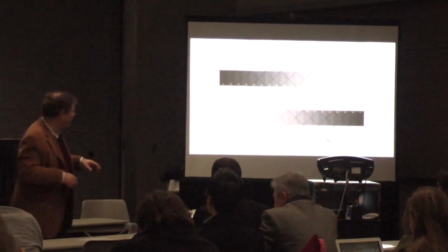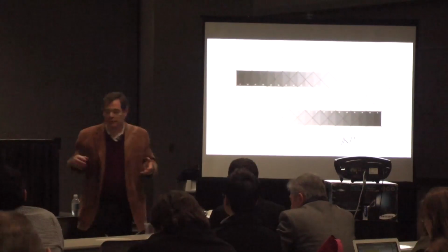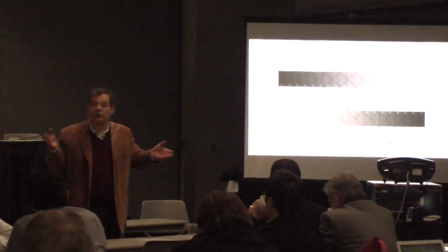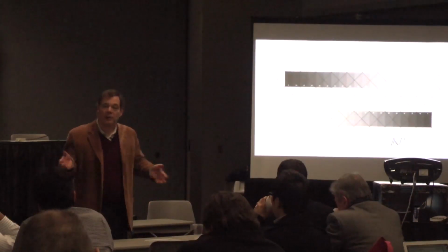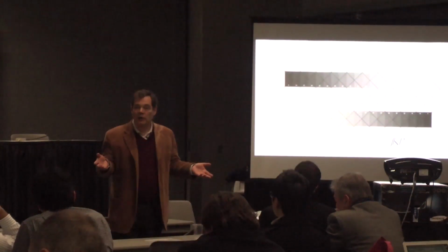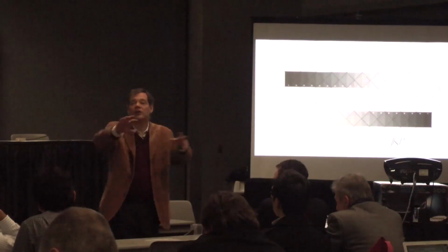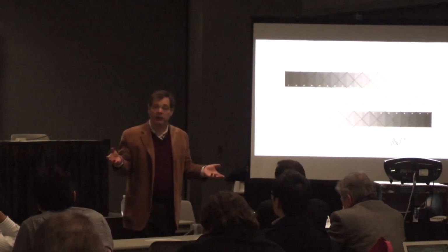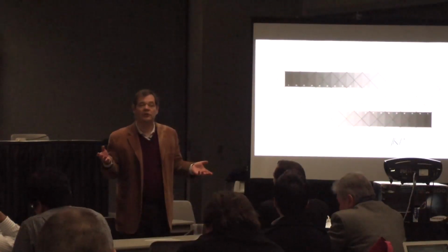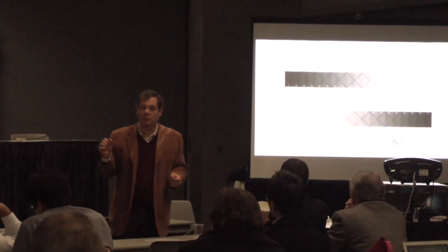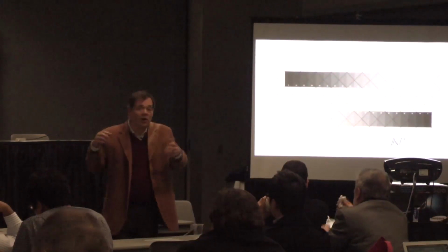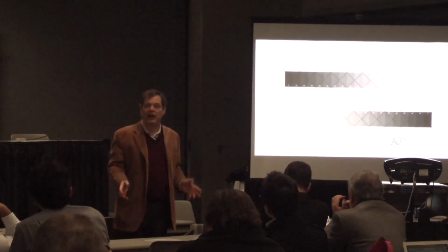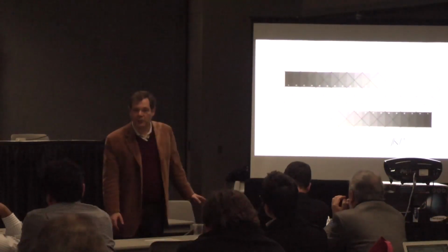As an example, 2.5% above black is a barely noticeable difference if you've got a gamma of 2.4, but if you have a gamma of 2.2, there's a huge difference. So are these numbers accurate? They are only accurate at a gamma of 2.4. They can only be accurate at a single gamma point, and if you're running any other gamma in the display, these numbers are not right.